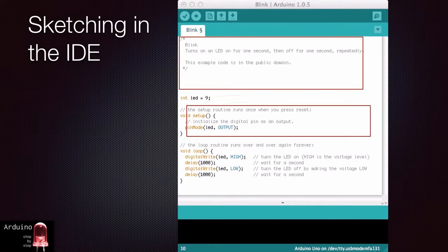An Arduino program can be broken down in parts by using functions. Functions make it easy to create little programs within a large program and to call each of these programs by name. In this example, we used two functions with names setup and loop. These are special functions that the Arduino will call itself. When the Arduino starts, it will first call the setup method and execute any commands it finds inside. Then it will call loop again and again until you turn off power, every time executing whatever commands it finds inside.